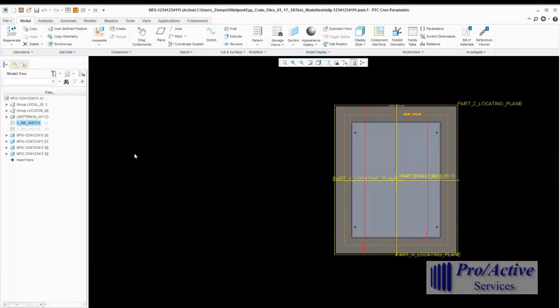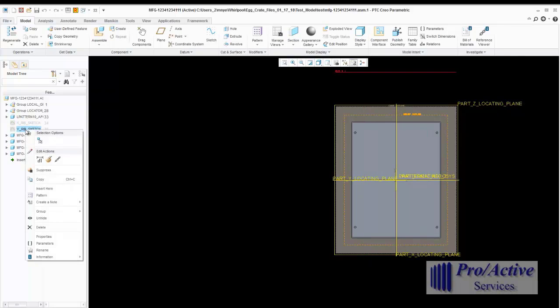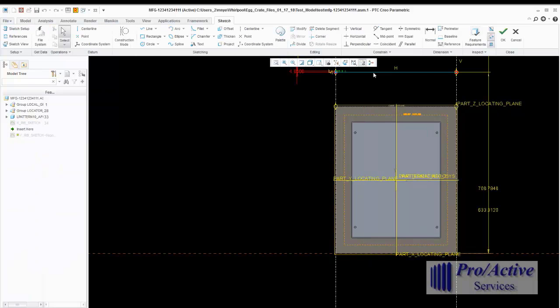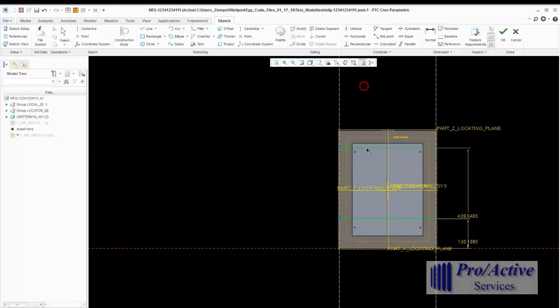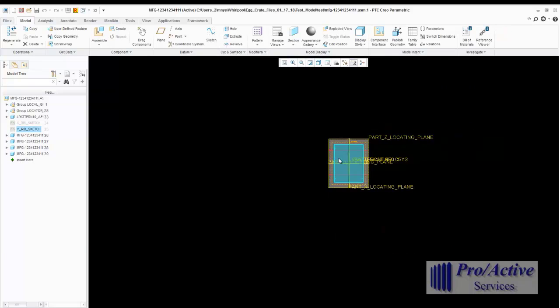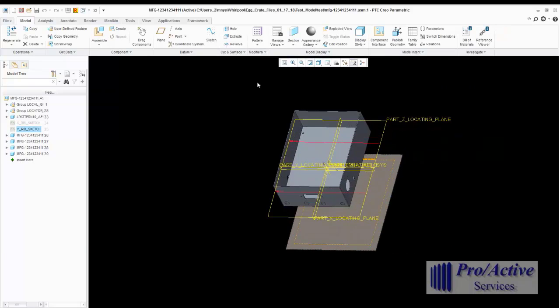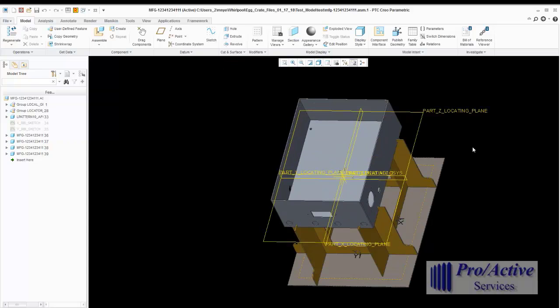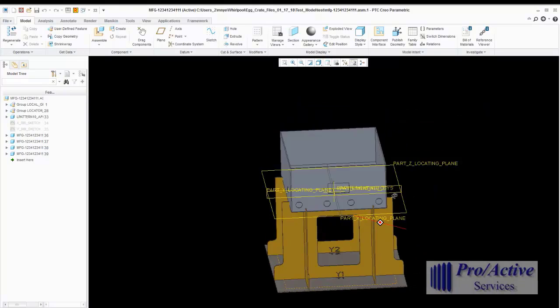Now I'm going to do the same thing for the ribs in the Y direction. Take this one, drag it down about here. Drag this one down there. Now I'm going to ask my model to update. I can see all the components for my egg crate fixture appear.